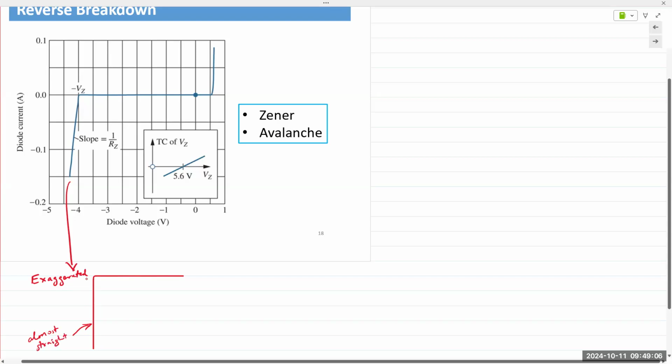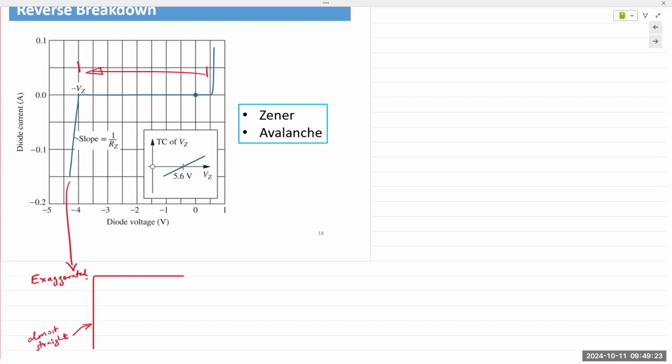It finds useful applications in real life. So for a long time, nothing will happen. This voltage could be very large, 50 volts, 100 volts, 200 volts, 400 volts. Nothing would happen to the diode, depending on how it's manufactured. And then after a certain point, the breakdown effect occurs, and a large number of carriers flow through the junction, and a reverse current results.